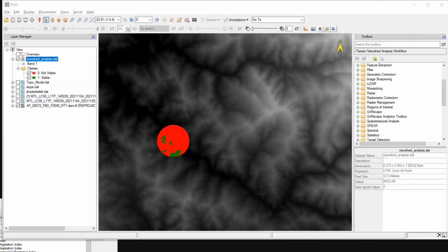A basic difference between optical and SAR, as can be seen here, is that towards the left we have the dark fields or the dark areas. If we compare the optical and the SAR, the SAR would show a dark field because the ground is wet or has moisture in it, and the brighter pixels are maybe because the crop is growing and there is a lot of backscatter.